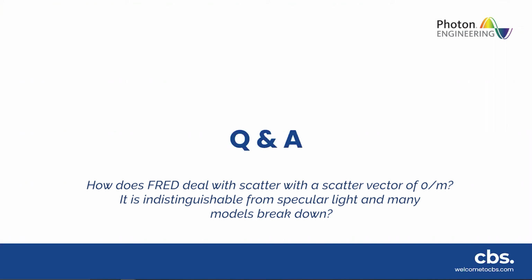When you have an angle of incidence of say 30, the specular reflection data point for 30 will be missing. It'll be there for 29 and there for 31, and I believe we then would interpolate between those two data points. So yeah, you have to remove the specular ray from the BSDF scattered measured data. So hopefully that answers your question, Martin. If not, feel free to contact me after the webinar.